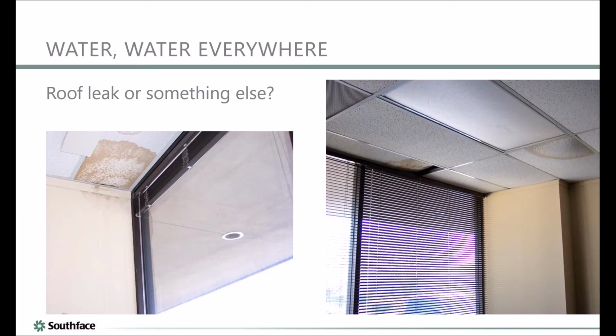So yeah. And a lot of times too, you'll see here, you can actually see the water stain, but you can also notice the ceiling tiles are kind of saturated and they're sagging. Mm-hmm. That's another indication that there's moisture. To use a poker term, there's a tell, something that reveals there's a problem here. And that's a classic example. So again, this was a spec office building that could be located anywhere in the country, right, and just had a certain amount of overhang and a leak path.